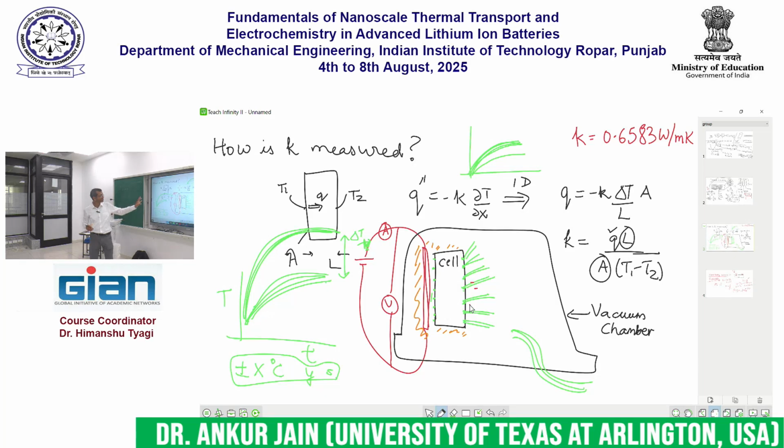We are trying to run this measurement at room temperature. Strictly speaking, the temperature difference should be extremely small so that I am measuring the thermal conductivity exactly at room temperature, right? In other words, I need to provide just a small puff of heat and measure the small temperature difference that occurs as a result of that. I'll never be able to do that, right?